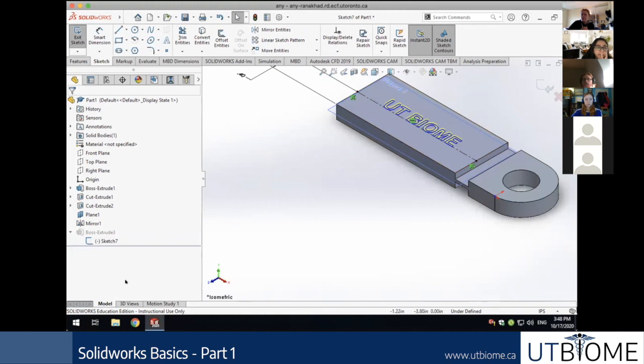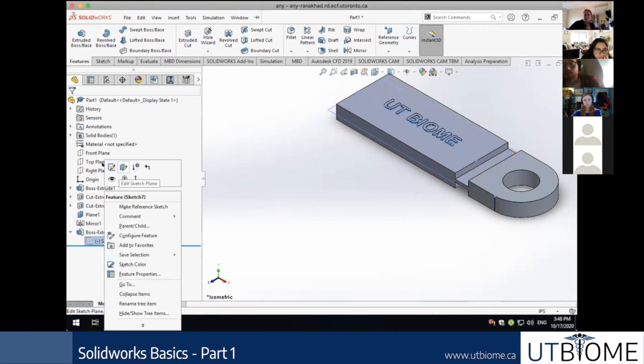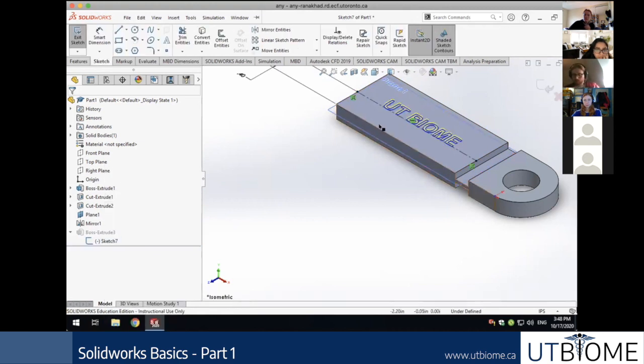And then once you escape and save that sketch, go to the top right where the big red X is, and don't hit the X, but hit the other icon. I don't know what you'd call that, arrow and squiggle. So if you were theoretically to have altered it, then it just would have updated and SolidWorks would have done the rest of the work for you. Whatever change you had made would be showing here basically.